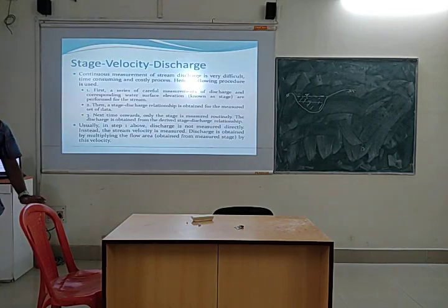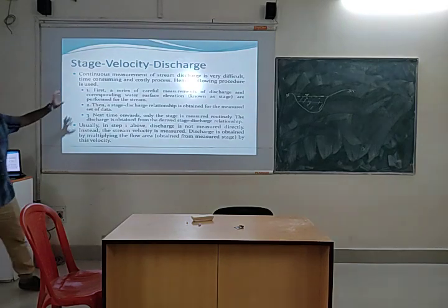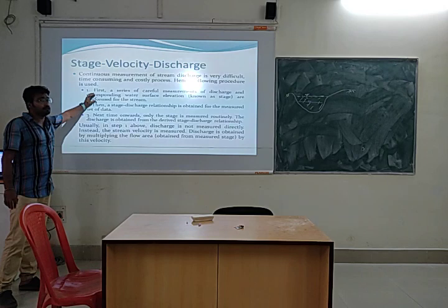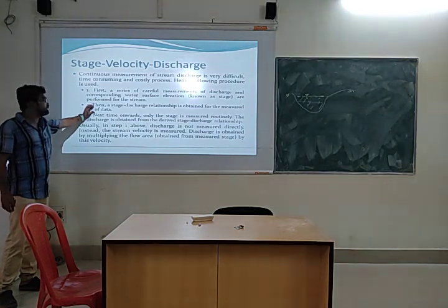Secondly, what we will do, obviously all the time we will not find out the discharges. Secondly, the stage discharge relationship is obtained for the measured set of data. So we are finding out what is the relation. We are selecting some set of data and finding out the relation between the stage and the discharge.